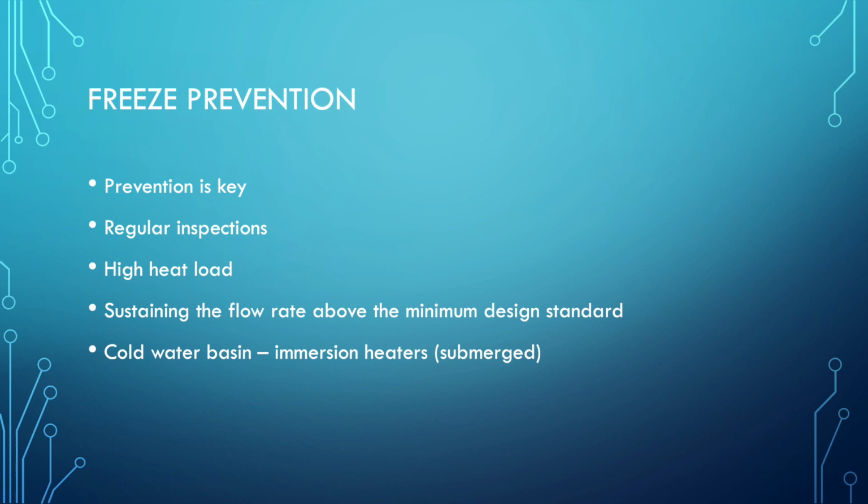So going into freeze prevention, you want to prevent it. It can happen, and if it happens, you have to turn off the water, heat it up, and then slowly turn the water back on to see if there's any cracks. But I'm going to talk about how you prevent it.